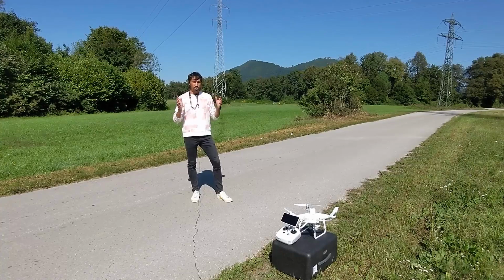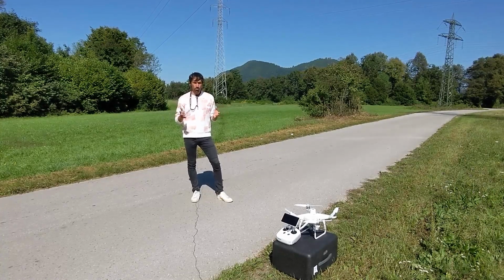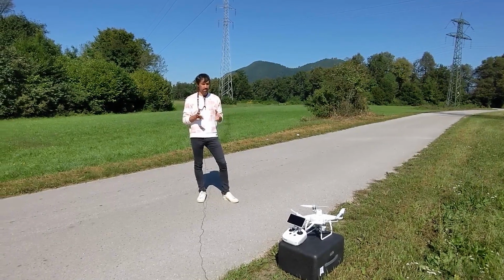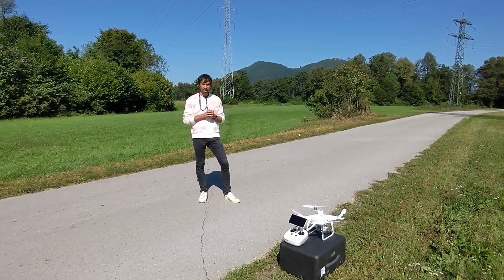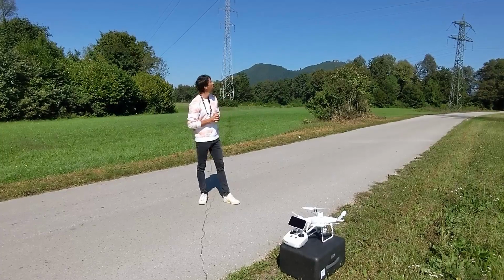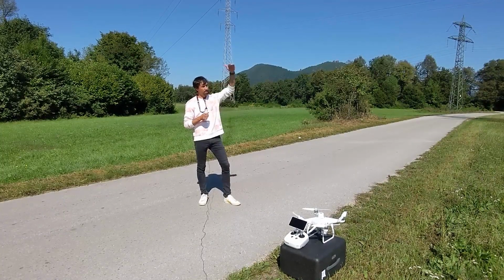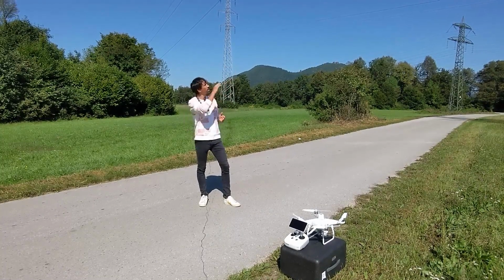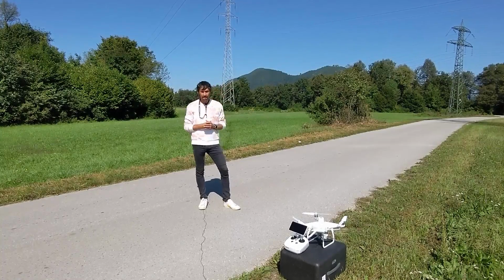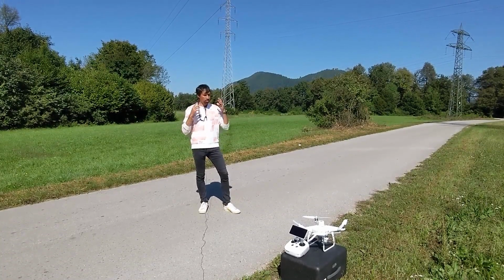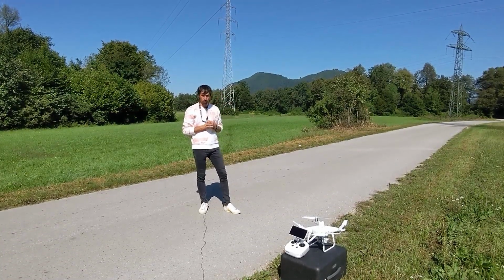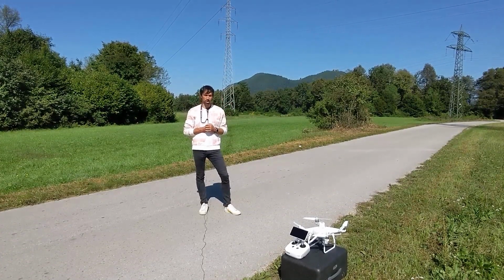We are not going to use ground control points for this project because the accuracy with the integrated RTK GPS is more than enough for this kind of project. We need more or less relative distances between cables and terrain, and accuracy is more than enough without ground control points if you use such an RTK drone.